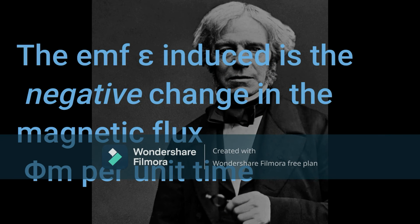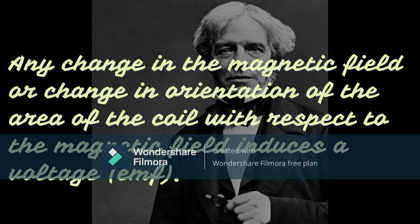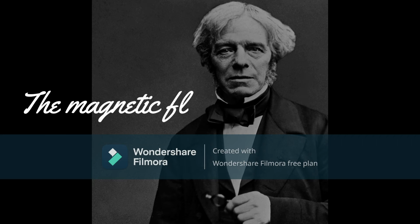As we see in the formula, the electromotive force induced is the negative change in the magnetic flux per unit time. So Faraday's law states that any change in magnetic field, or change in orientation of the area of the coil with respect to the magnetic field, induces a voltage, which is known as the electromotive force.